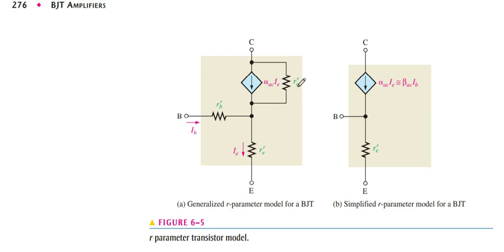As rc is very high compared to rb and re, we treat it as an open circuit, and rb is very small, so we can remove it and make the circuit in this form.